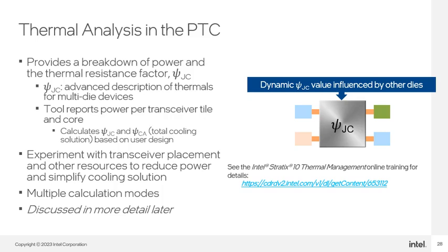Each silicon die has its own power usage and thus also has its own junction temperature. The different die areas cause heat to leave each die at a different rate. Thus, thermal management in these devices must ensure that each of these dies are below the specified operating temperature, and the overall thermals are defined by which silicon die heats up first.